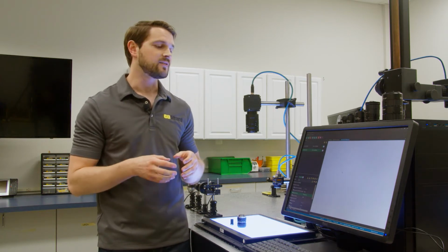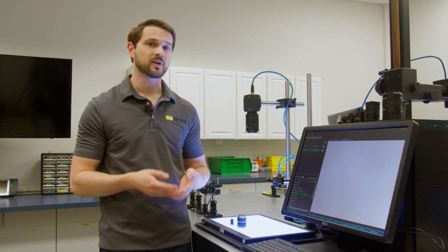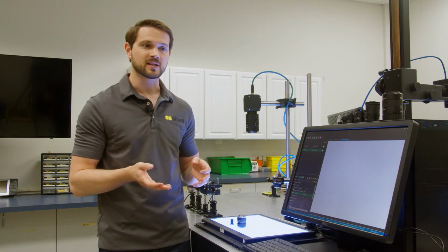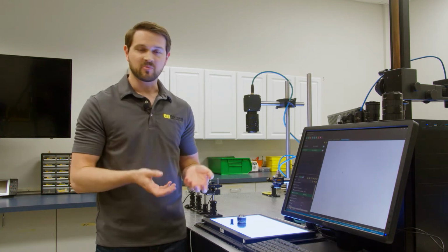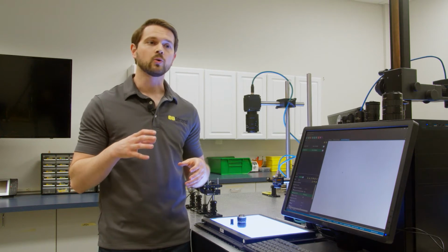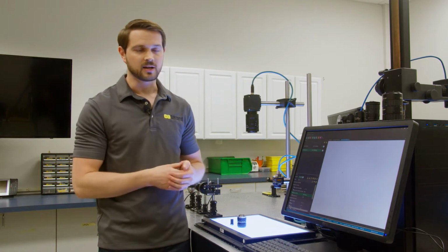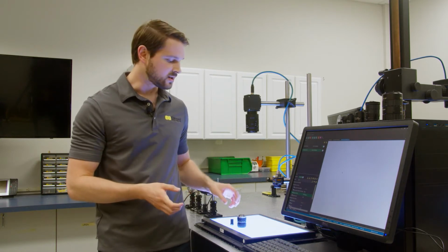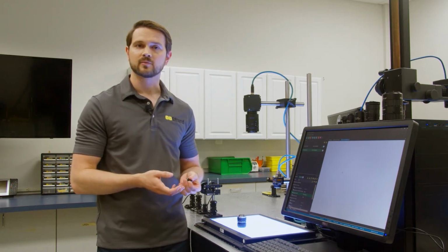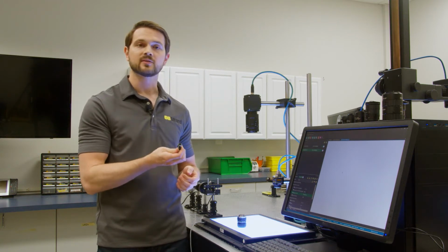Now, if you look at what the actual nominal dimensions are on a 1-inch sensor, they're 6.4 millimeters by 4.8 millimeters, and it has an 8mm diagonal. Now, I'm pretty decent at math. I'm not the best at it, but it is impossible to make any of those numbers correspond to a 1/2 inch, right? It's actually an old notation that comes back from imaging tubes. I'm not going to dive into too much of those details. Shoot us a question if you want to know some of those details. But essentially what we do is we look at the diagonal of that sensor, which in the case of a 1/2 inch is an 8mm diagonal, and we match the lens to that diagonal.